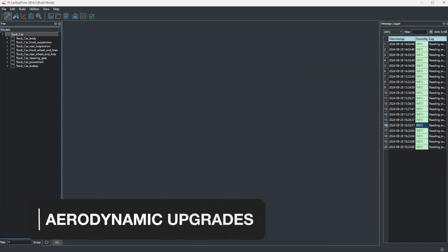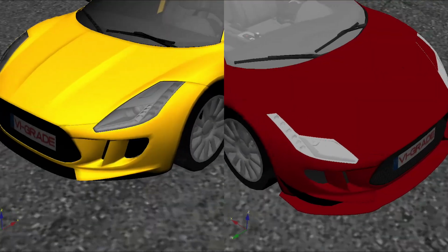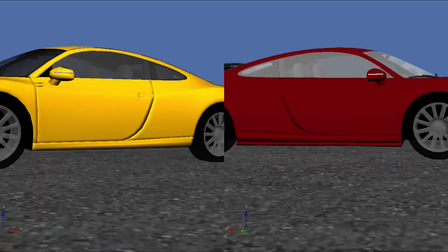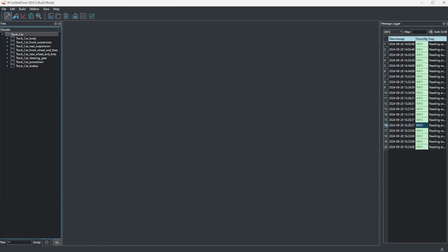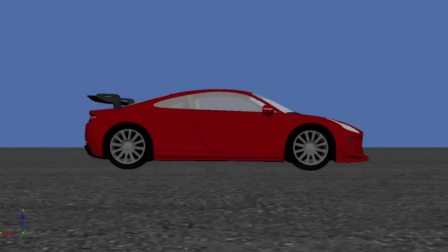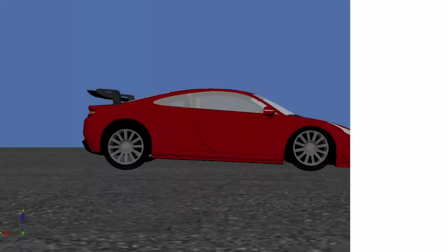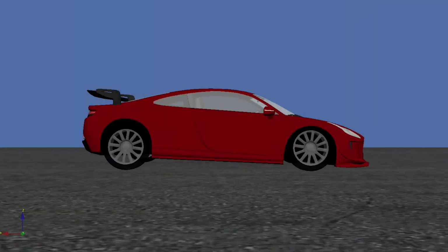The aerodynamics package we will install in our car is composed of a rear wing, a new splitter, side skirt extensions, and modified rear bumper and diffuser. With all the new components positioned, we can still optimize further the aerodynamics performance by adjusting the front and the rear ride heights, which will influence the airflow around the body. This is a powerful tool in high-performance vehicles.